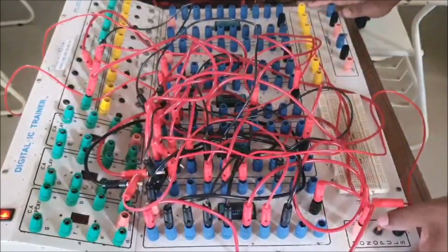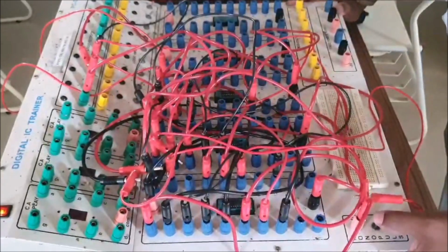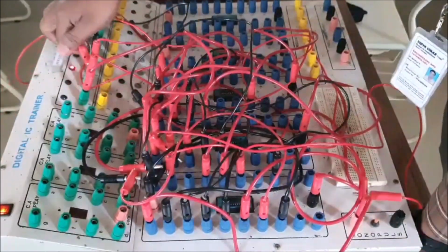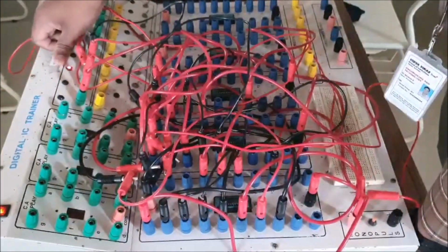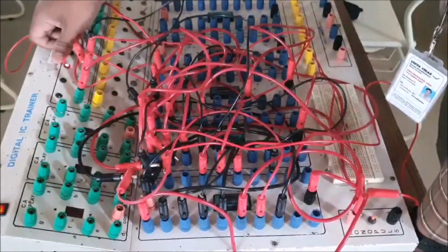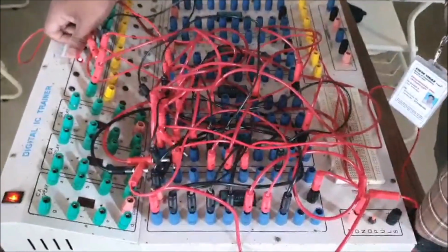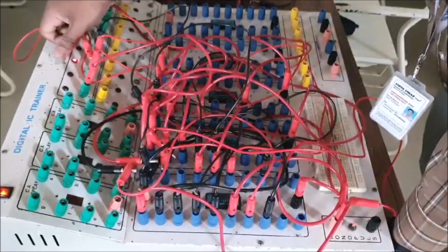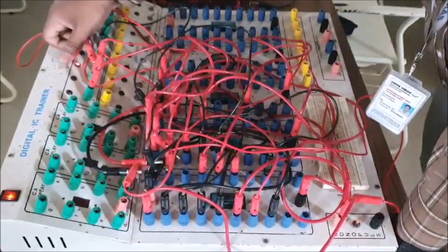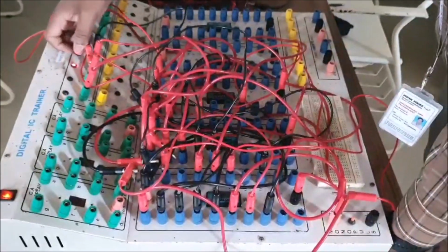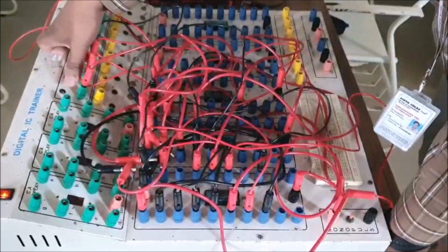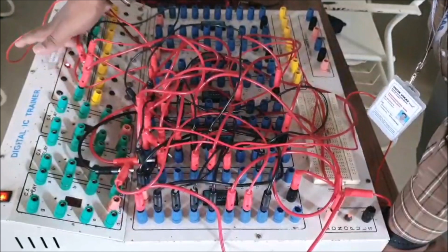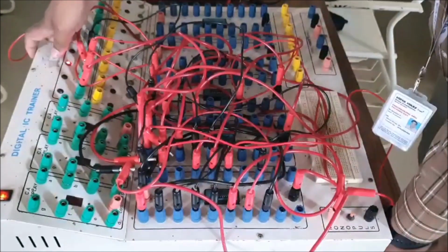Now I will press the monopulse clock. When I press the monopulse clock once, I get the output 001. The LED light emitted from QA results in the value 1, which means that QA is equal to 1, QB is equal to 0, QC is equal to 0. So the binary representation for the decimal value 1 is 001.